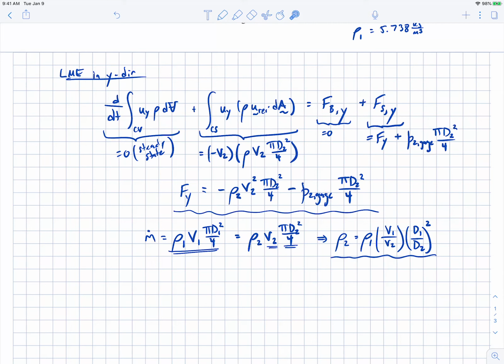And this one is a little bit trickier. Now, I don't think I've mentioned it in lecture yet, but in pretty much everything leading up to this point in the course, we've said that when you have a free jet, the free jet's pressure is equal to the surrounding atmospheric pressure. And that's true if the flow is subsonic. If the Mach number is less than 1 at the outlet, then it is definitely true that the pressure in the jet will equal the pressure of the surrounding atmosphere.